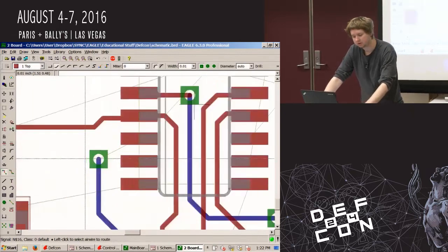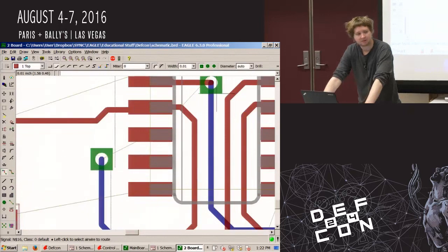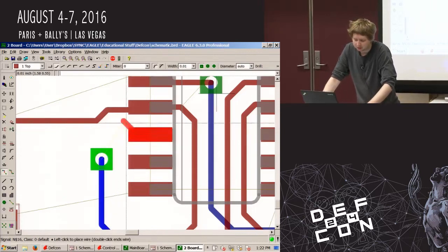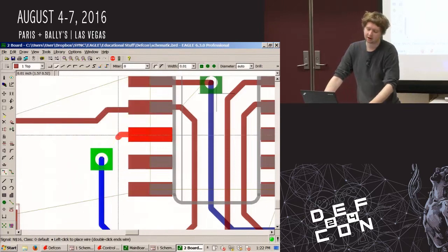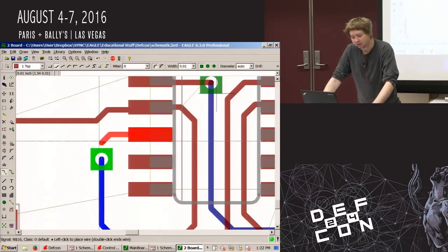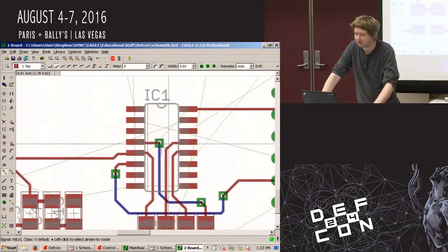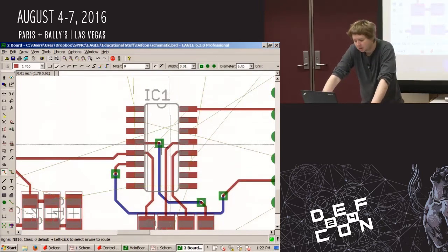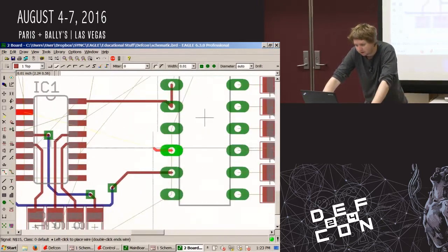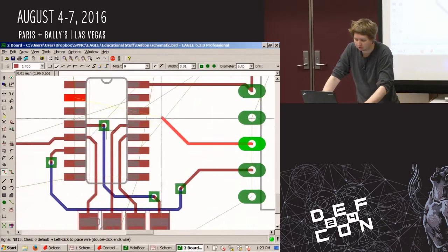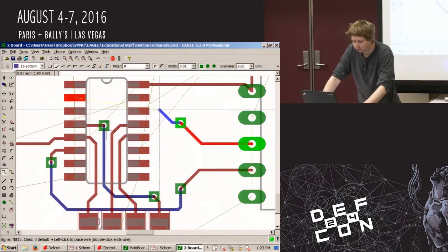And something I also like to do is I like to end wherever it is I'm going to be ending, and then I start the trace again from the other side. That puts me right in the middle, because you can tell in the pad above that I'm not right in the middle, and usually it doesn't make a difference, but because I design boards where I only make one-offs and stuff like that, I like to spend some time on aesthetics. And because I also build all these by hand, I'm the one who has to suffer through any board decisions. So I do the best I can to make a good board.